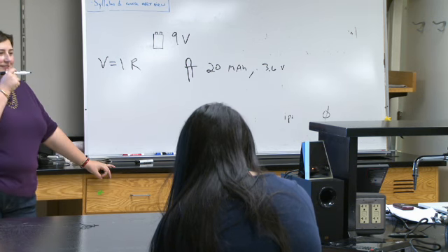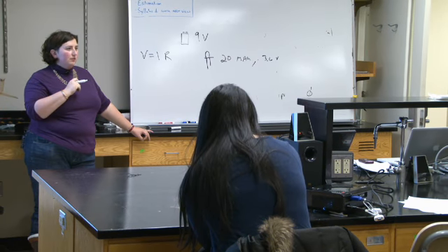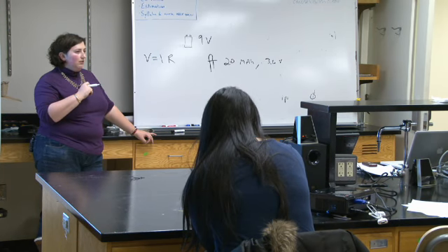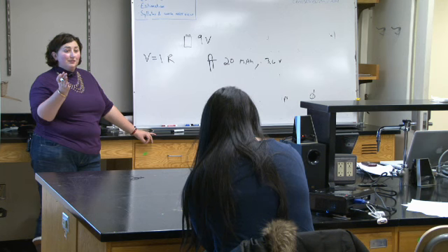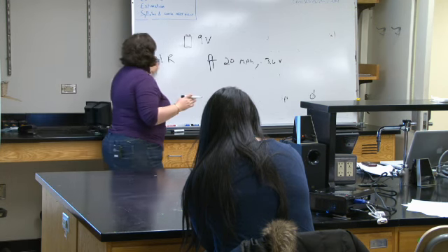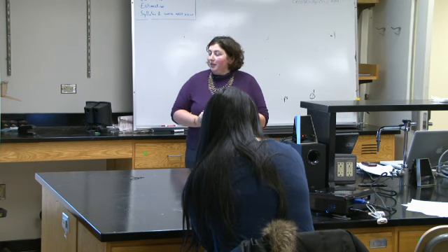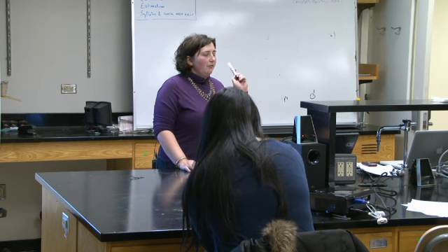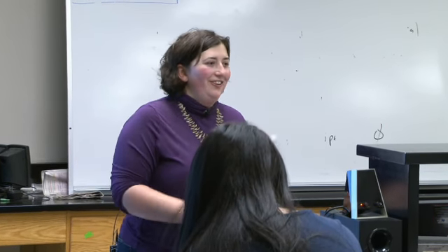Yeah. So you know that you have the remaining voltage that you need to drop before the circuit finishes off. So you need to drop off that much V in your resistor, and you know what the current is because it's 20 milliamps. So divide it. Yeah, exactly. Are there any questions? Okay, cool. So I'll explain the assignment, but that's going to be very useful. All right, so that would be another reason why you need to use that information: if you don't use a resistor, you're going to blow your LED, and you only get one, so you don't want to blow it.